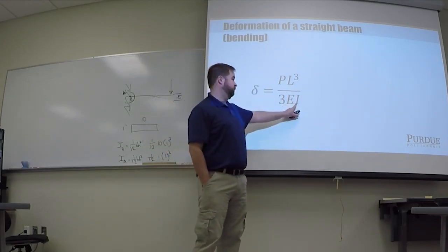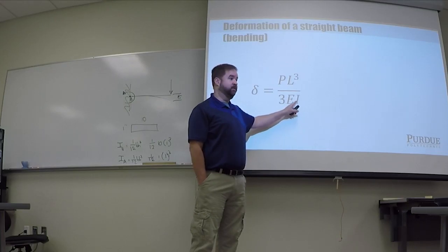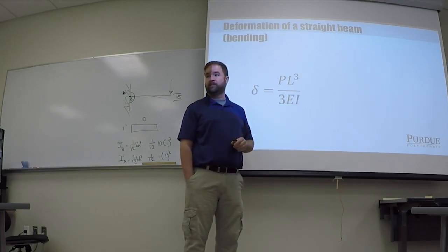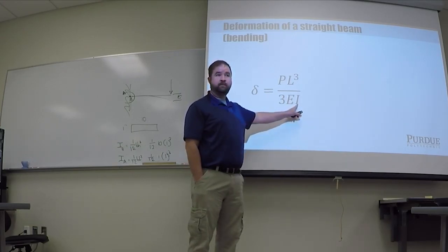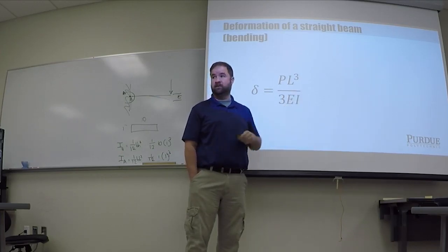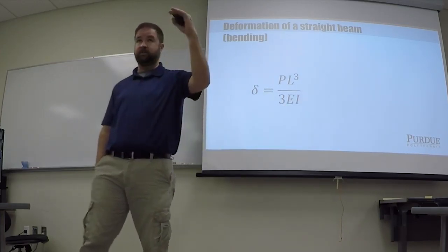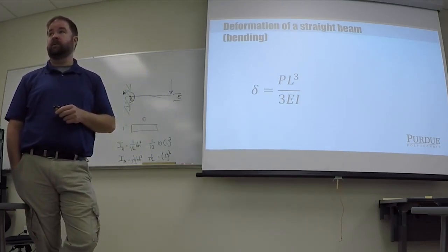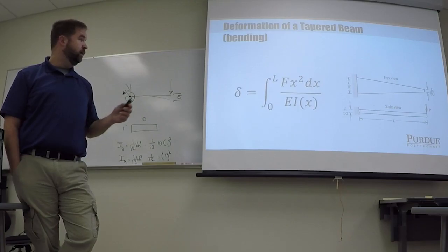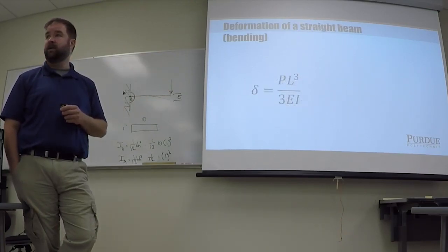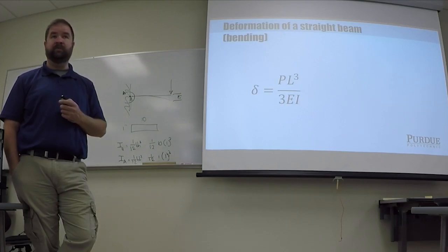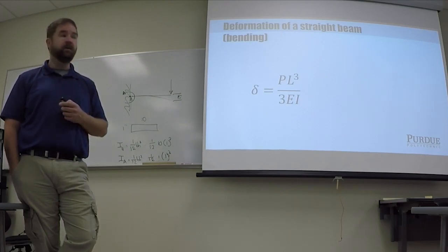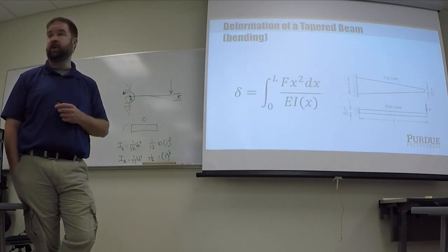Okay, what do I use? Well, if I think about that, the factor is 0.171. So I'm probably going to have to use the small I, IA, in this equation, right? Because the IA is going to give me way too big of a deflection, then I'm multiplying that by 0.171, which then brings it down to the right value. Okay, so using this table, in this equation, you'd use the IA value, you multiply it by the 0.15, whatever it extrapolates to, and then that gives you the correct answer for the tapered beam problem with a hand calculation.